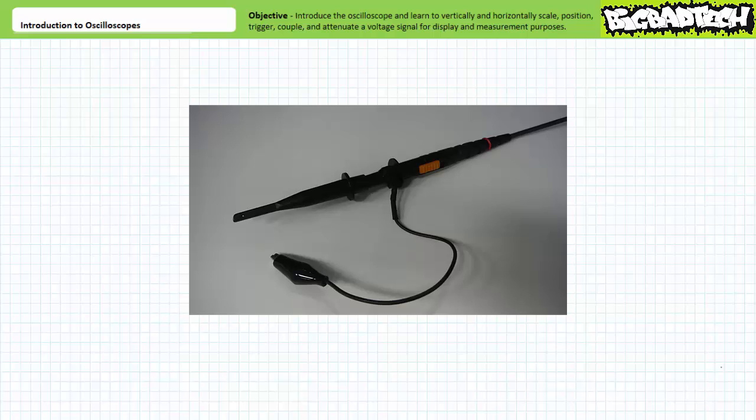An attenuation of 1x means the value isn't attenuated and the probe will deliver 1 volt to the oscilloscope for every 1 volt differential experienced at the grabber. In contrast, an attenuation of 10x means the value is attenuated 10 times and the probe will deliver only 1/10 of 1 volt or 100 millivolts to the oscilloscope for every 1 volt experienced by the grabber. Does 10 times attenuation mean division by 10? Yes it does.